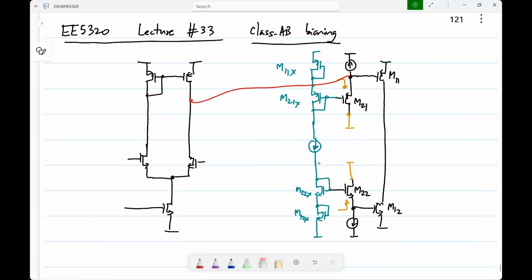I'll come back to the problem I had given in one of the older assignments. What is done is the following. This is connected there and this is connected over there. That is the circuit you had analyzed. In that case, what will be the impedance looking into this? Whatever current goes here comes back through that. So what is the impedance looking there? It is infinity. So it is not loading the previous stage anymore. On top of it, this current goes this way, through this GM. Whatever incremental voltage is here will also appear at the gate of M12.